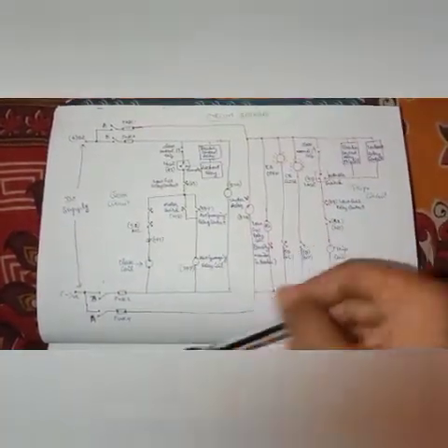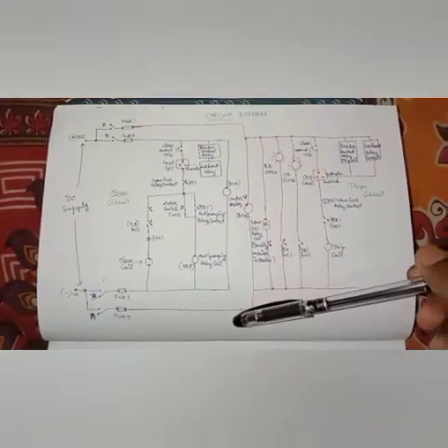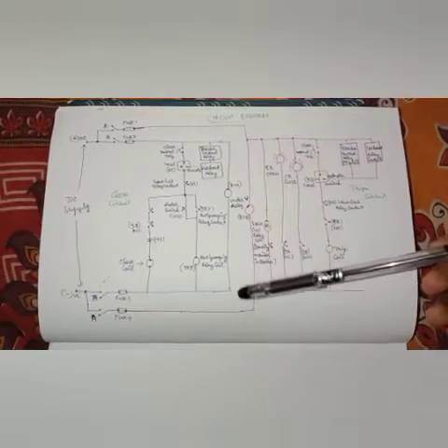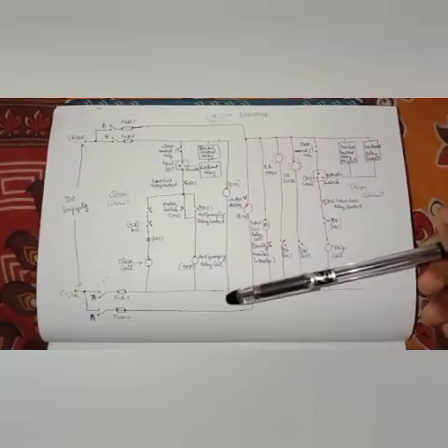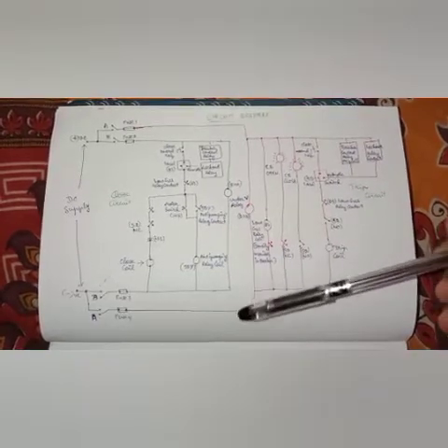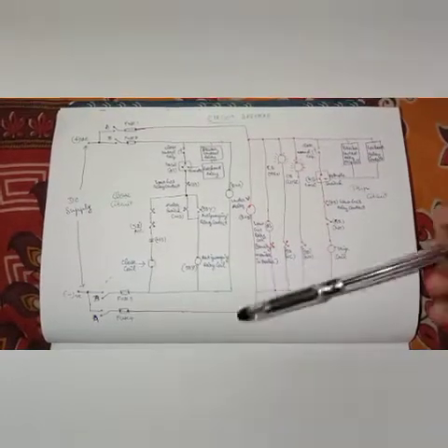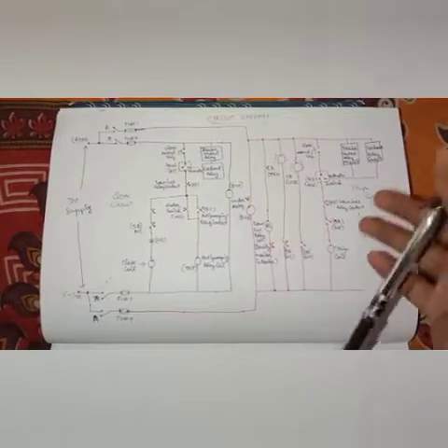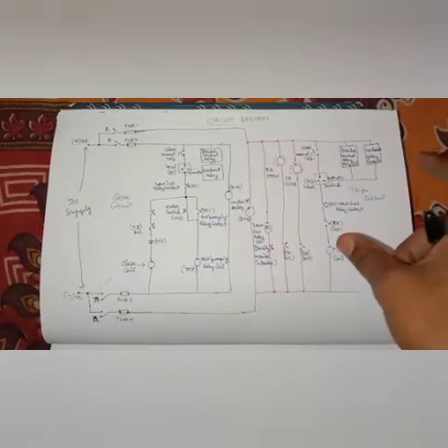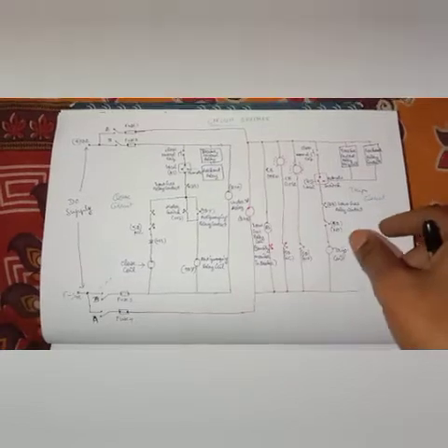So this is your very basics of your circuit breaker diagrams. Further, in practice it will have more pages by additionally adding the pole discrepancies, the spring charge status, spring charge operations, AC, and also the mechanism and marshalling boxes separately, because in a three-phase circuit breaker each phase will have a separate mechanism box, and all those mechanism boxes will be connected to your common marshalling box.